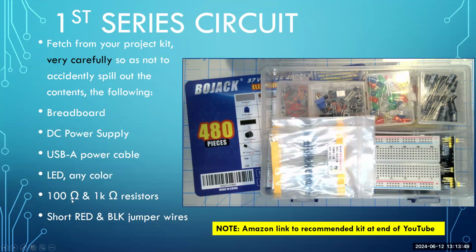Now, this is a symbol for ohm. This is the Greek letter omega, and it represents the unit for resistance, and 100 ohms is a certain amount of resistance. 1K is 1,000 ohms. So you pull out one of each of these. Only pull out the 100 ohm initially, one resistor at a time. I'll tell you why later. Then also a short red and a short black jumper wire.